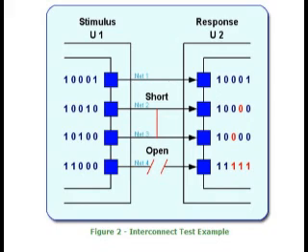Boundary scan tool vendors provide various types of stimulus and sophisticated algorithms, not only to detect the failing nets, but also to isolate the faults to specific nets, devices, and pins. Interconnect test example. Boundary scan applications.